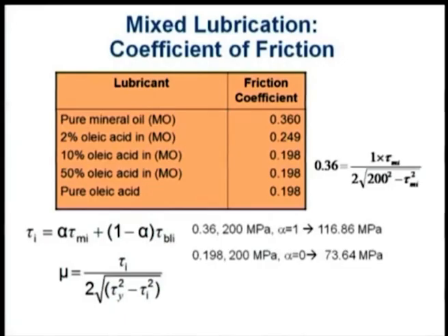in absence of boundary additives, but the liquid lubricant acted very nicely. It gave some interface, a sliding interface, able to reduce the shear strength of the interface, and that always happens. Wherever there is adhesive bonding, use a lubricant, then there will be a slippery action happening there, and cold weld junction will not happen if there is a slight relative velocity.